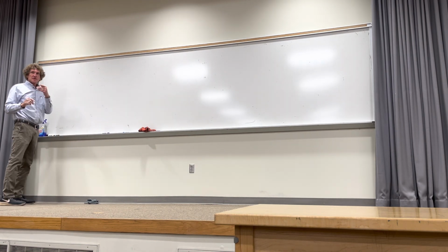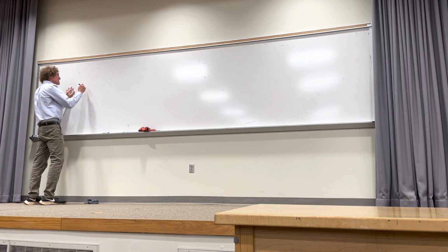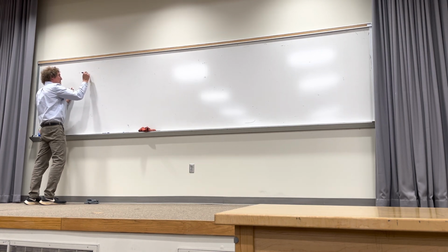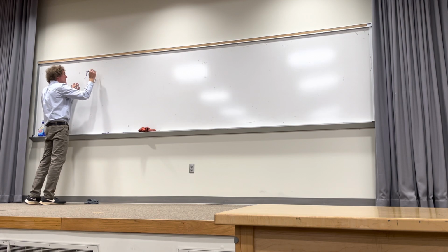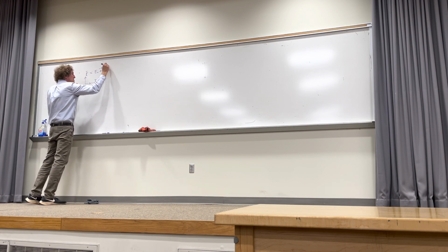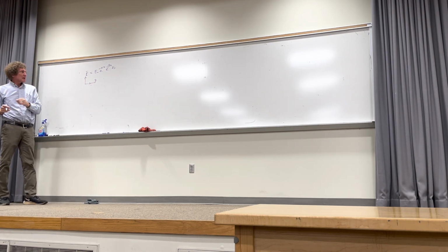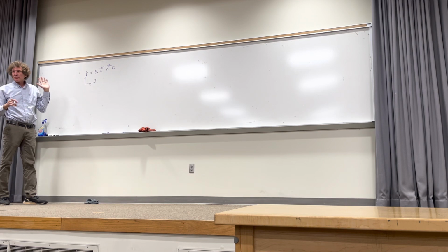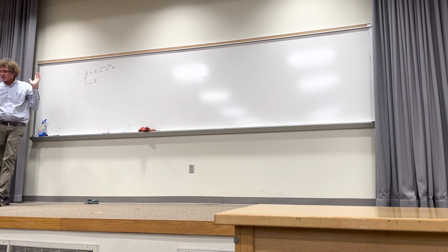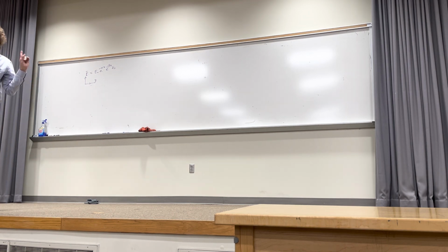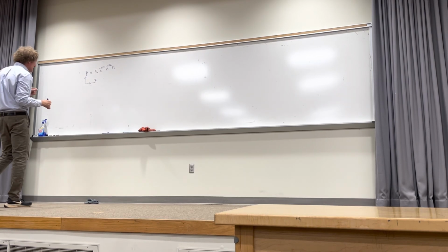So I'm going to stick with his standard way of denoting things. And he says, if you have an electromagnetic field polarized in the x direction and it's propagating in the z direction, the E field would be given as simply some E naught e to the minus alpha z times e to the minus j beta z, and then it's going to be ax. That's the phasor form of the E field. Y'all follow me on that, class? It's propagating in the z, but it's oriented in the x direction, right? Now that's a standard plane wave, and it comes from a solution to Maxwell's equation with the assumption that we're far from the source and we have an E field with one polarization, with one component that's propagating in the z direction.